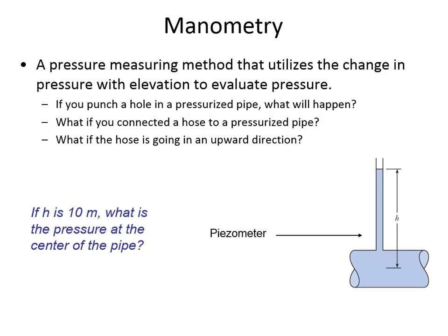Okay, so calculate. If H is 10 meters, what will be the pressure in the center of the pipe? How could we use this piezometer as a way of calculating the pressure?